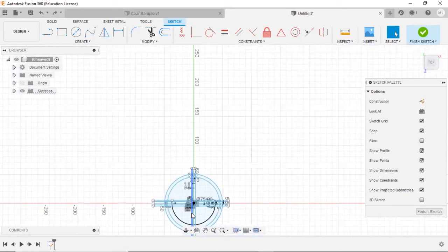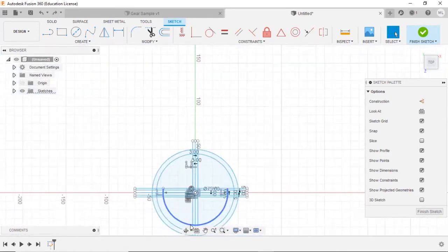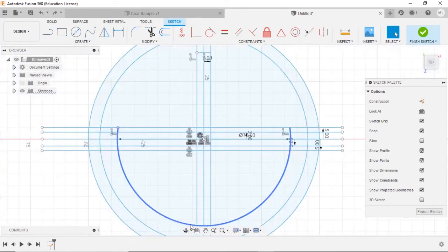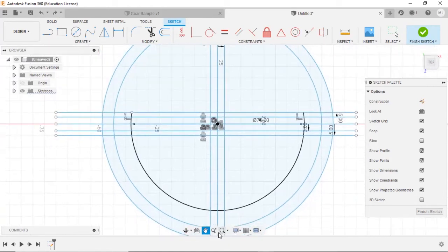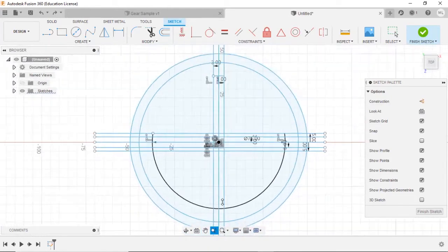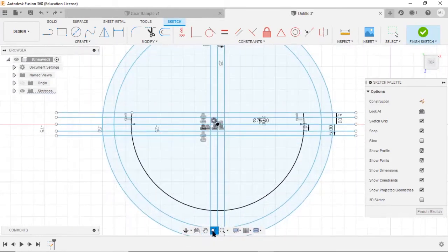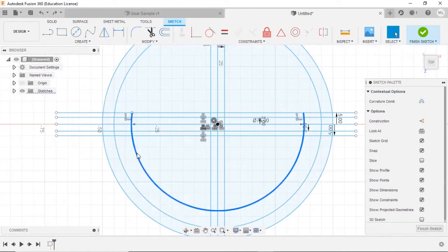To further improve your work, to scroll down or scroll up your work, you can use this one, zoom. No, it should be zoom in and zoom out your work. So you can use the zoom part or pan to move. Zooming in, zooming out. Or press Escape. So in this case, we'll be deleting this particular arc.